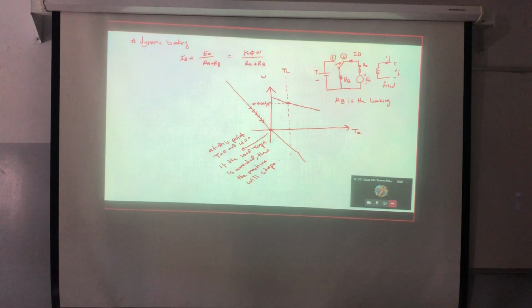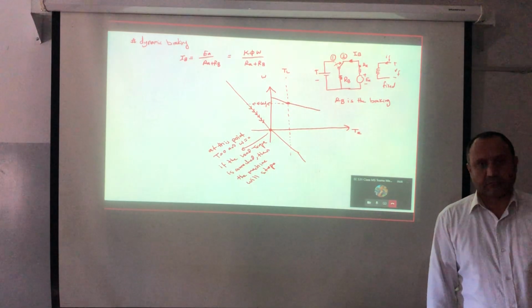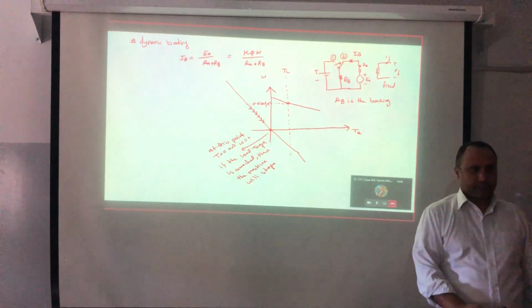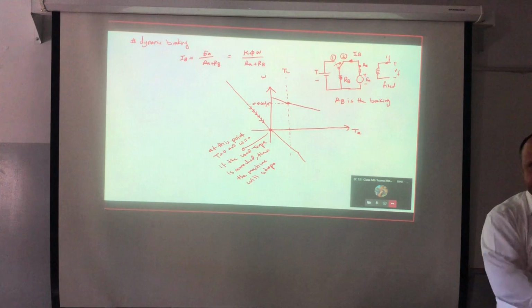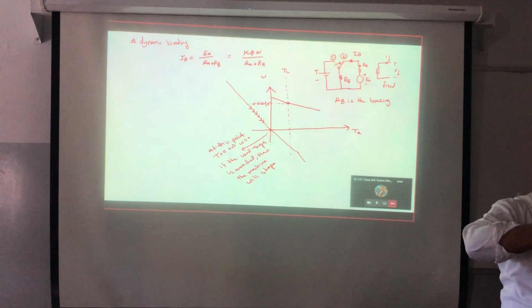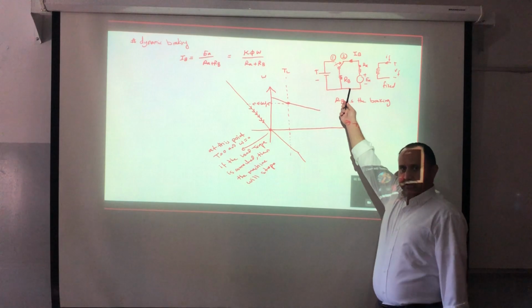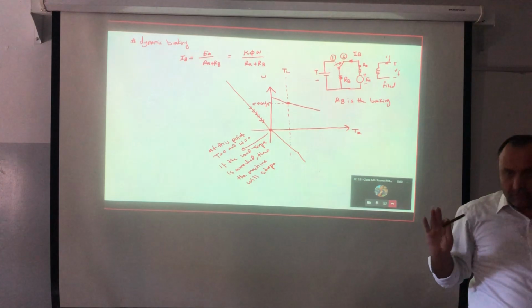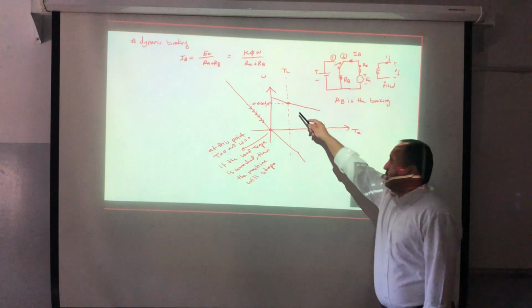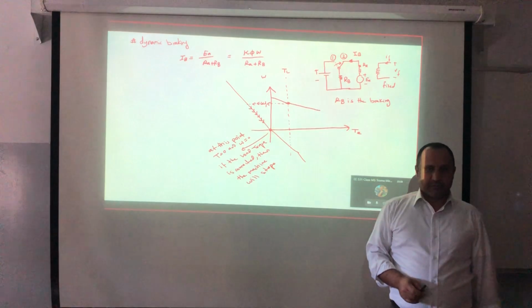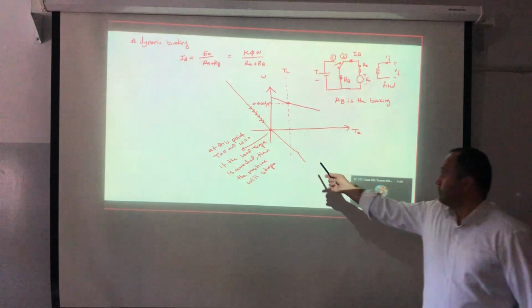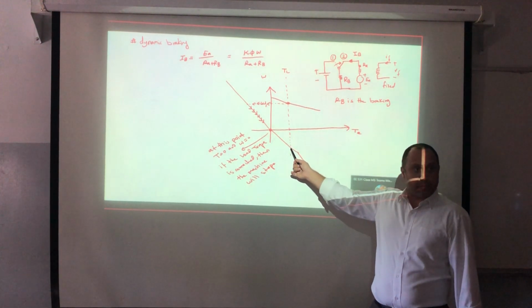Yes or no? Before we remove the load, shouldn't the machine stop or not? But it is accelerating. Just a minute. If the load is connected, what will happen? Only I'm doing dynamic braking, which means that I'm disconnecting the voltage and only adding a braking resistance, and I think you all understand why I'm adding that: to limit the braking current. Now, if the load is there, where will the operating point be? This one. So the machine will never stop.